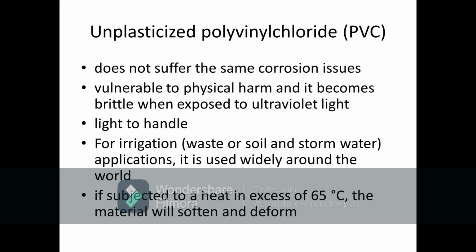But if subjected to heat in excess of 65 degrees, the material will soften and deform. So for fluids such as hot oil, this is not a material you want to choose.